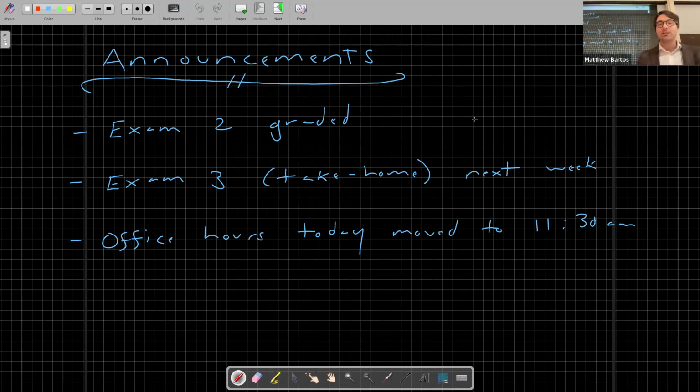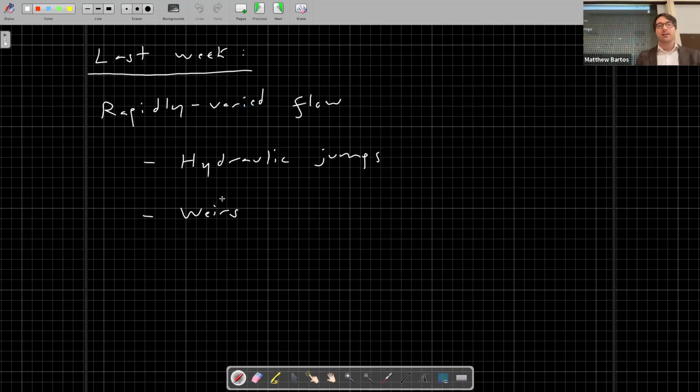All right, well, let's go ahead and start today's lecture. So last week we covered rapidly varied flow. We covered two cases of interest. We first talked about hydraulic jumps, where we have a rapid transition between supercritical flow and subcritical flow. We talked about how we could compute the sequent depth and velocity downstream of a hydraulic jump, given the depth and velocity upstream of the hydraulic jump.